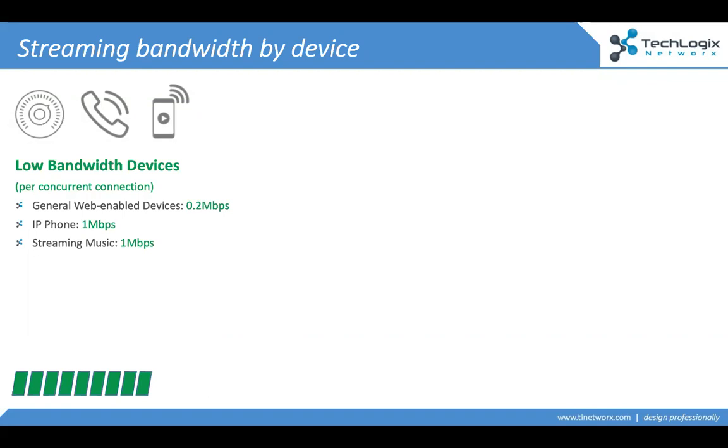If anybody on this webinar today is working with the commercial world and you're doing an office building, you know that there comes a point at which a lot of IP phones require a pretty strong backbone, okay? What do we find with IP phones? Well, on average, the minimum required connection is 1 megabit per phone, okay? Now, granted, will some phones be used all the time? If I have a call center, for example, will all 100 people there be on the phone at the same time? Maybe, maybe not, but we've got to plan for it, right?